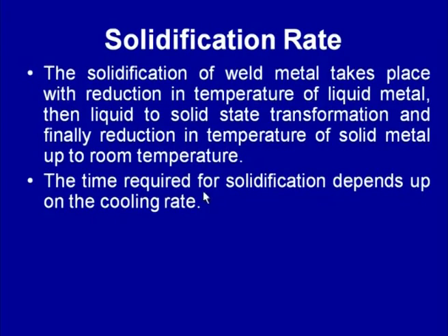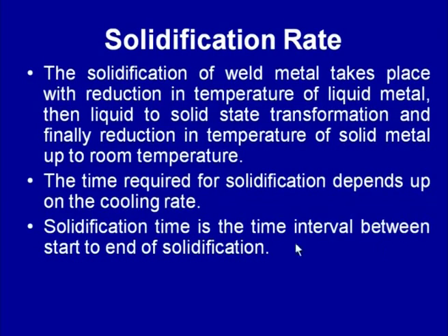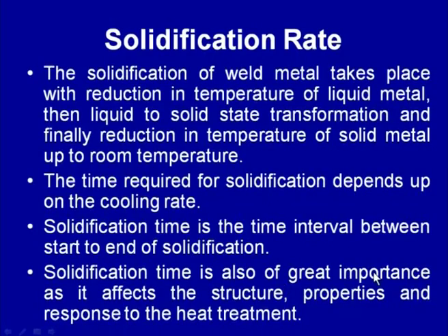The time required for solidification depends upon the cooling rate. In general, the higher the cooling rate, the lesser the solidification time. Solidification time basically is the time interval between the start and the end of solidification, and it is of great importance because it affects the solidification structure, properties, and the response to heat treatment.